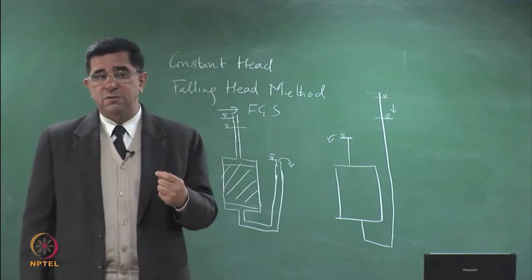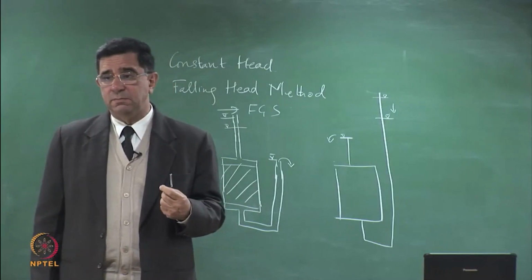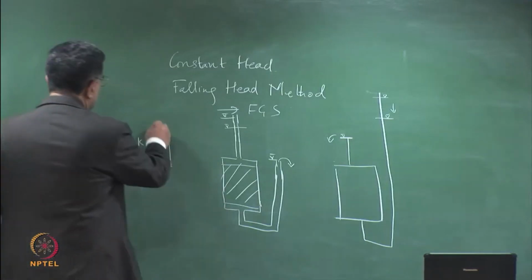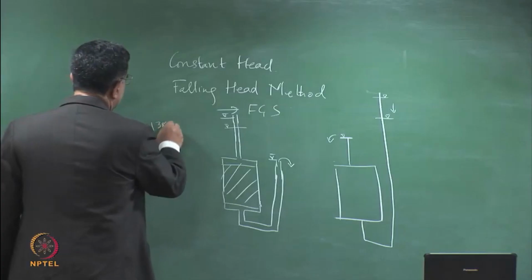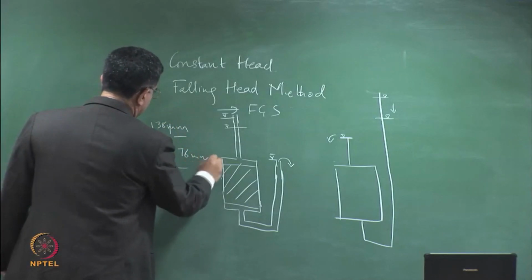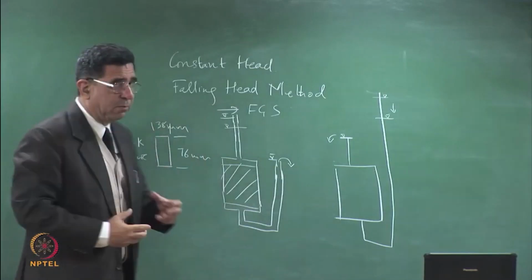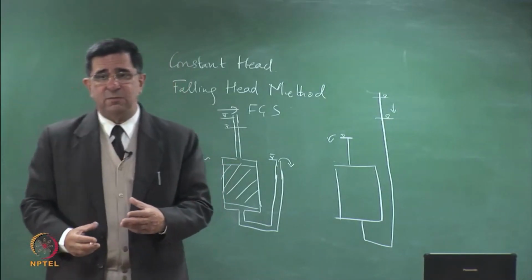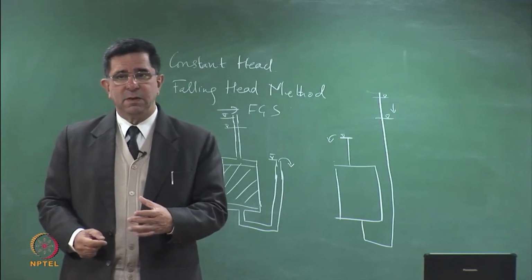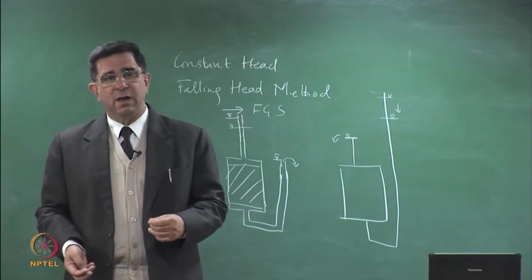In a consolidation test, we also saturate a sample. The size of the triaxial sample is 38 millimeters and 76. And does the shape of a consolidation sample, is it similar to that of a triaxial sample? You remember consolidation ring?